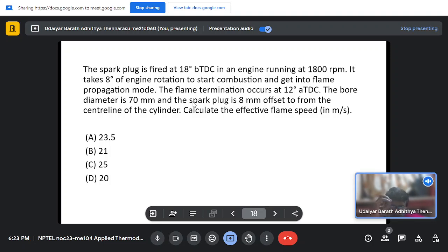So what you do is, you fire the spark plug before it reaches the top dead center. And the whole combustion also requires some amount of time to take place. That is all calculated using the valve timing diagrams and the spark plug ignition. So here they are saying that the fuel-air mixture which is coming in, the piston goes down and starts compressing. At the top dead center, it has reached the total compression, and ignition will start.